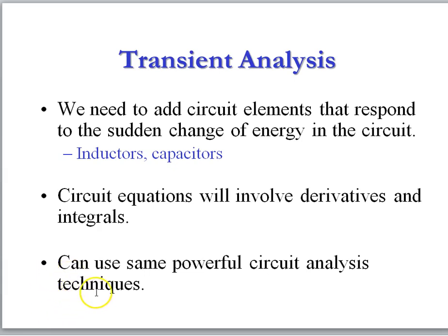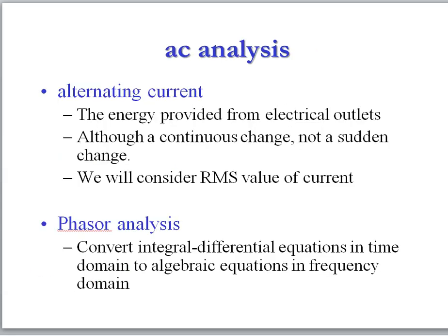So from there, however, when we get to integral differential equations, when they get to third order or fourth order, it obviously becomes pretty cumbersome. So we'll start introducing next semester our AC analysis, and we'll be able to take our sinusoidal currents and voltages, we'll model them as RMS values of current, and we'll use a phasor analysis where we'll convert our integral differential equations in time domain to algebraic equations in frequency domain.